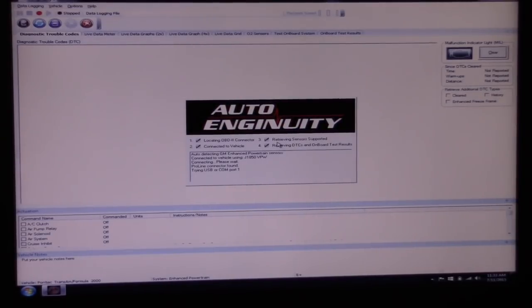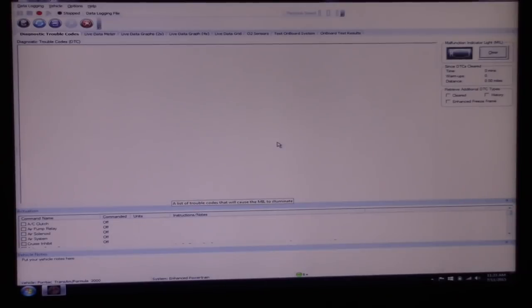Okay, and while this sets up, I already looked up my specifications in a service manual. It states that at idle, we're going to look for somewhere around 2,000 hertz, and at full throttle, as many as 10,000 hertz. Of course, that would be different with the car at park, sitting here, versus actually driving and having more air traveling through because of the speed of the car. But let's go ahead and see if we can find our PIDs.